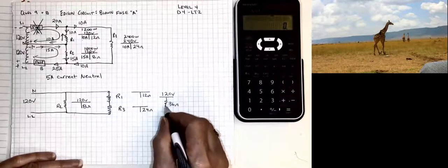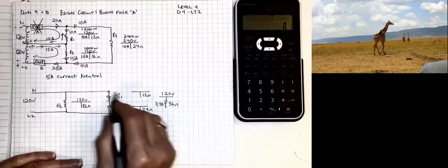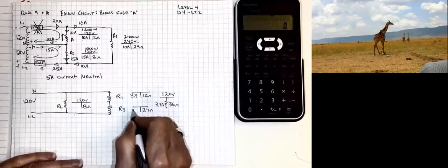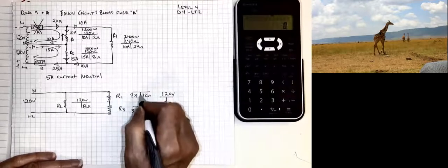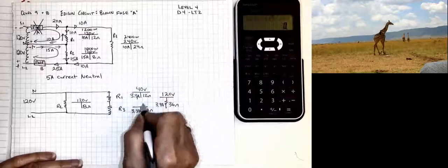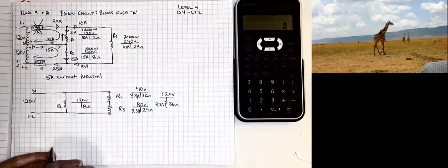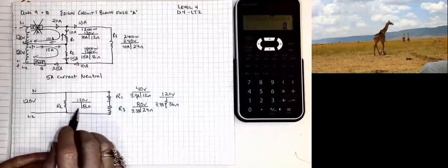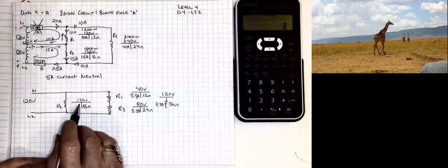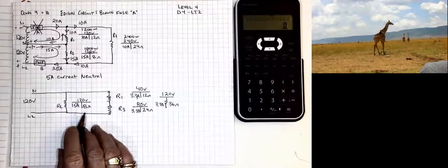120 volts across that equivalent resistance gives me 3.3 amps down this branch. Because these are in series, each one of those will get 3.3 amps. And now I have two numbers in there, calculated those out already. So we have 80 volts on the bottom one and 40 volts on the top one. And like I mentioned before, this has not changed. So that guy stays the same.